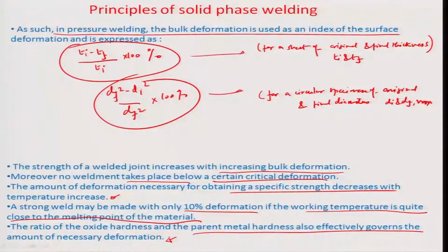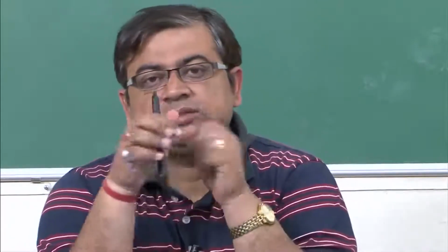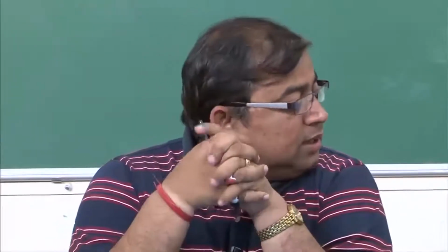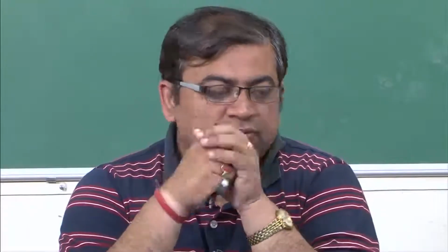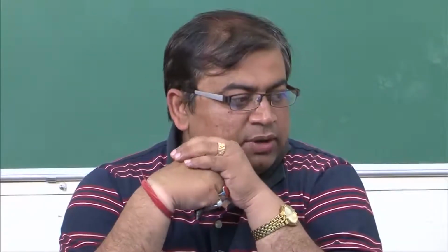So, the greatest hurdle which comes in case of solid phase welding are the oxide layers, and maybe some kind of oil films or some kind of separation films which would not allow the weldment to happen by making an intermediary layer, either which would have crack propagating effect or would probably have some kind of oil or impurity, not allowing the two materials to come to the closeness of that of a grain boundary. So, there are many methods which are used for taking care of such situations.